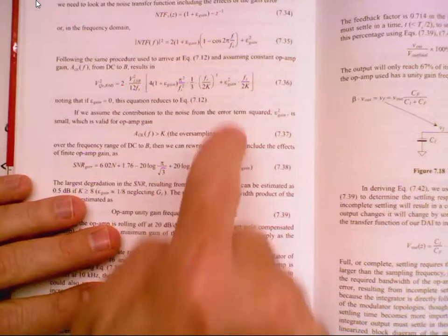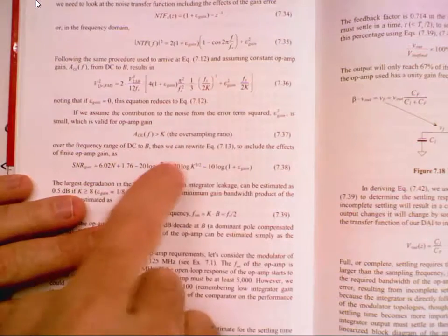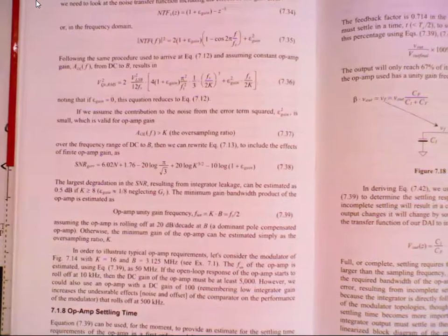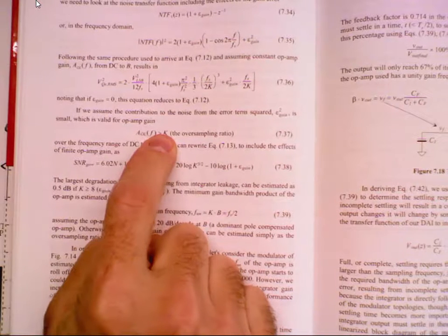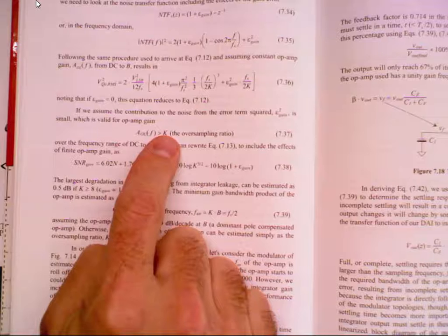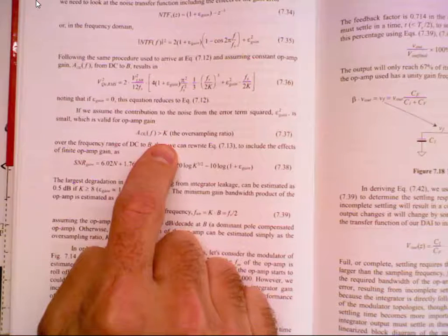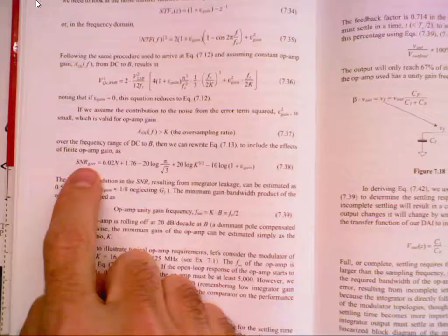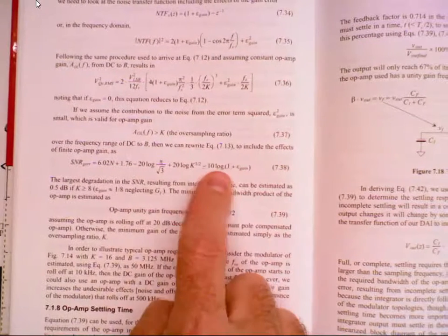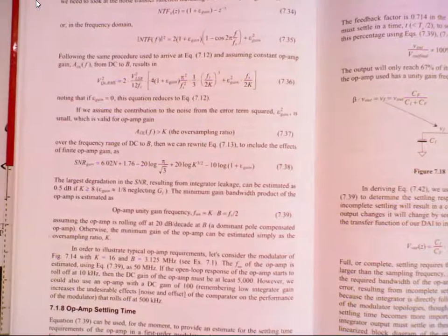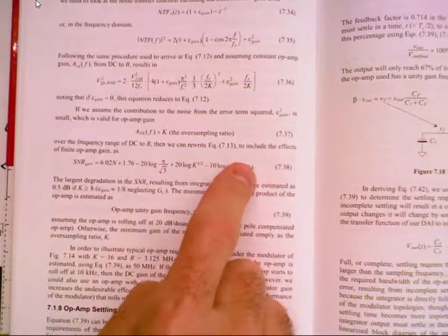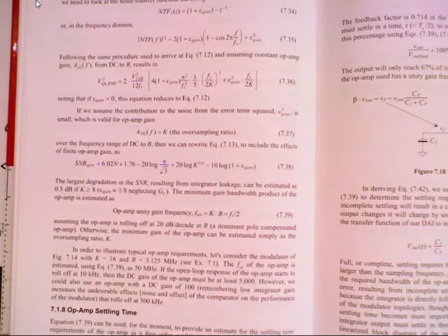The key point is, if this term becomes small, then I can just say, okay, well, I want AOL to be greater than K. So now here's where you say, okay, well, does the data converter fail if it's less than K? No, it just doesn't give you as high a signal-to-noise ratio, which is a big deal for manufacturability. You ask now, okay, well, how does it degrade the signal-to-noise ratio? You can go through the exact same derivation, and you can add the gain term here. Of course, if E gain is 0, then this term goes away.